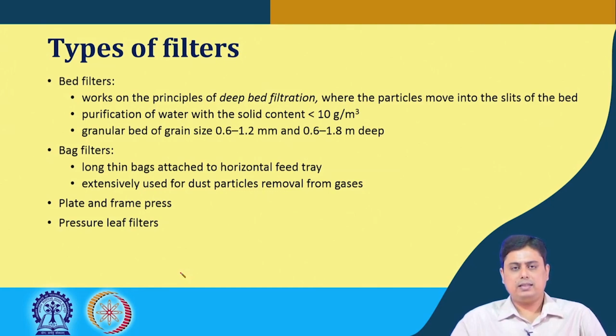In such cases, it has been seen that instead of conventional or the old traditional sand filters, if that bed is replaced by a granular bed that has a grain size of 0.6 to 1.2 millimeter and a depth of 0.6 to 1 meter of height, this effectively separates the suspensions from the water, so the solid particles from the water.